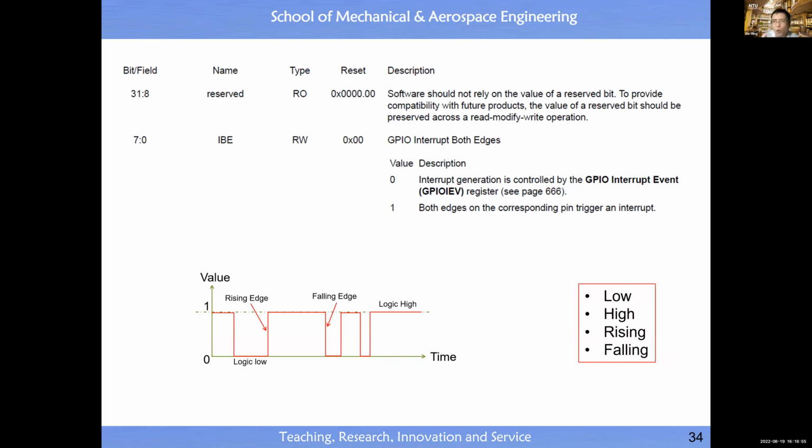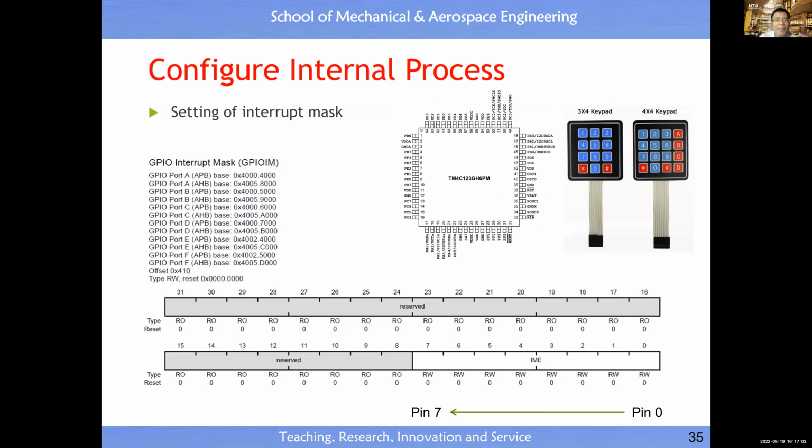In the context of motor control this is important, because once you press the emergency button, it must respond and stop everything. Once you define all these signals, for some periods of time you may say, I'm doing a certain type of activity, so don't interrupt me. Even if an active signal is produced at the input of the port, I mask it out. You can dynamically say, don't pay attention to this signal. So this is the interrupt mask.